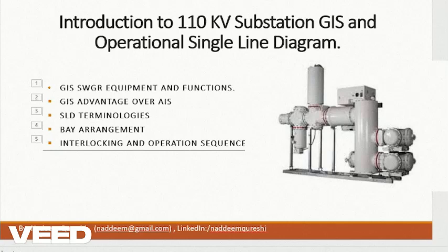Enclosed design prevents contamination and reduces faults. They need low maintenance because SF6 gas is used as an arc quenching medium and also the insulation medium. This reduces the wear and tear, extending the equipment life. And the safety is enhanced more than the AIS. So let us go to the next slides where we will be discussing the actual system.